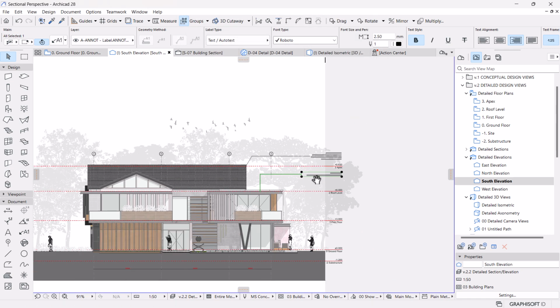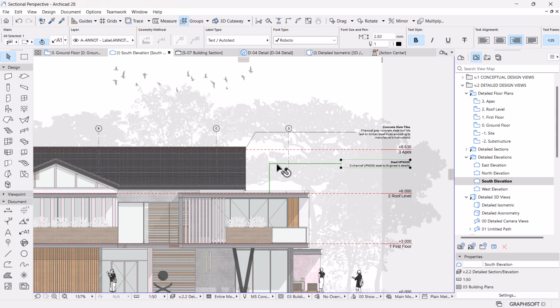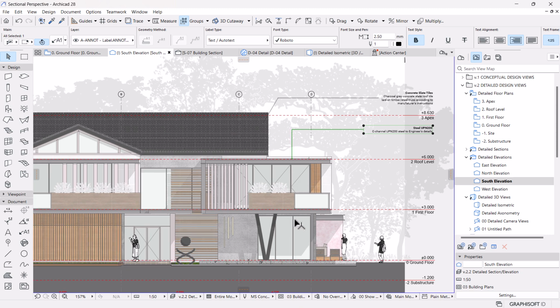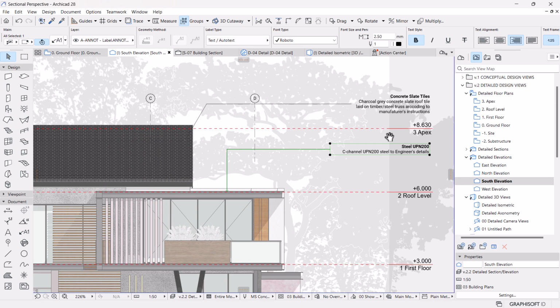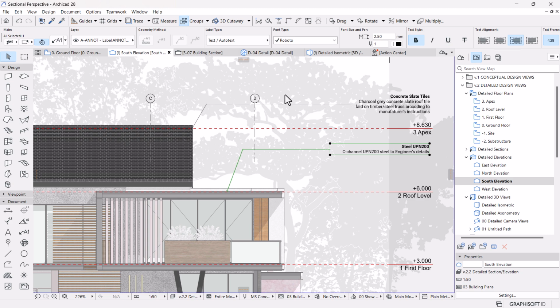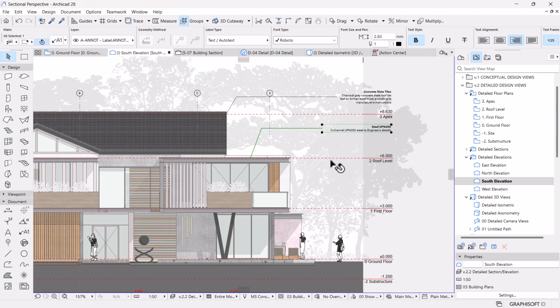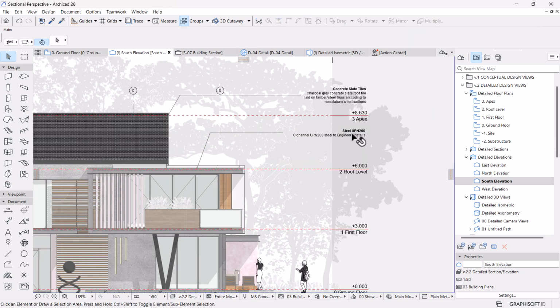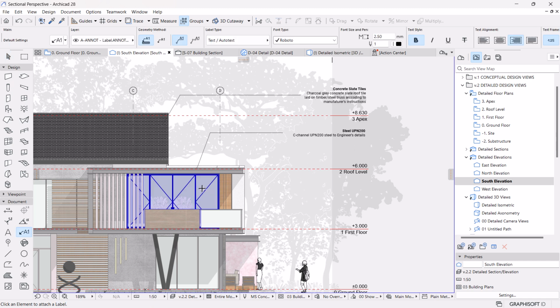But I don't like the 90 degree angle, because they will compete with the elements within the drawing, because there's lines. So I don't want that. Because this is secondary information, I want it to be slanted or angled so that you can reference it or pick it easily. So let's set it to maybe 60 or 70, something like that. Perfect.